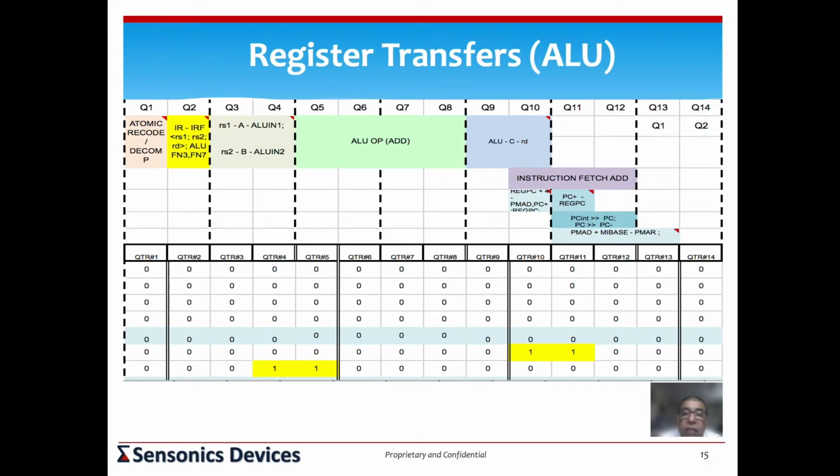So there are those kinds of functions here which we have not described, but when you start writing the register transfers and keep the data path drawing, which I showed you, by your side, you realize that some hardware resource has to be put into your data path. Otherwise, this function cannot be done, or the expectation that you have of that function will not execute. You will need more cycles to do an instruction, for example.